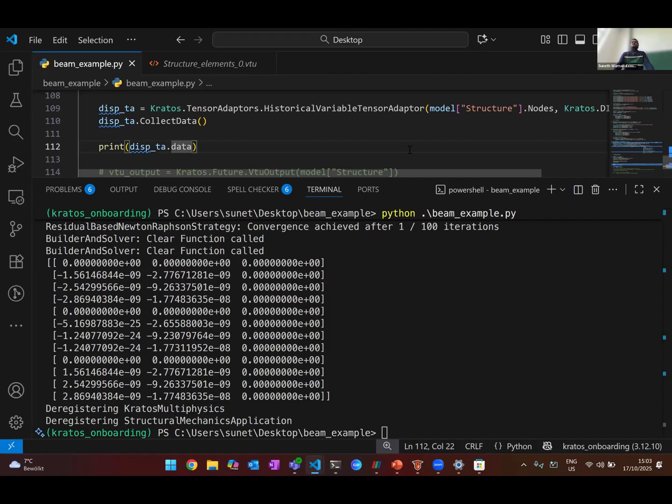And this one doesn't have a cost if you do it wisely, because NumPy allows sharing the backend memories of other software. So we don't do a copy in here. We just share the memory between NumPy and Kratos. So no copying involved to be efficient. Again, the efficiency comes into play. Otherwise, if you create a new NumPy array, you need to always copy, reserve memory, and all those things. We avoid everything. It's done automatically.